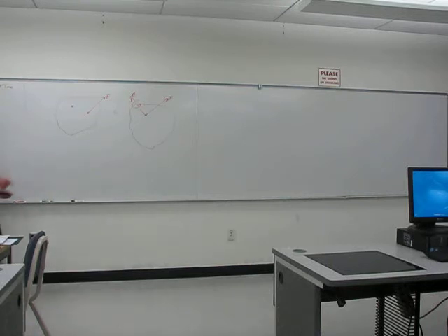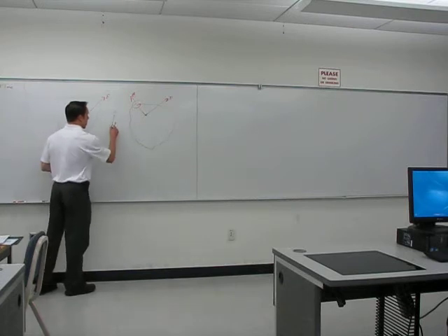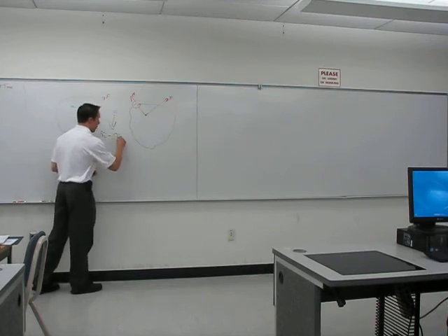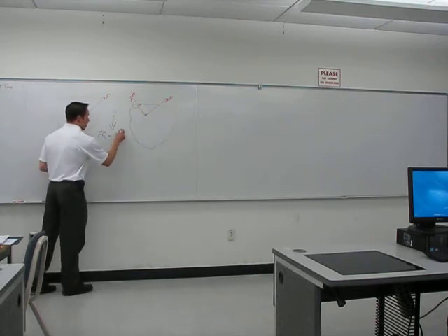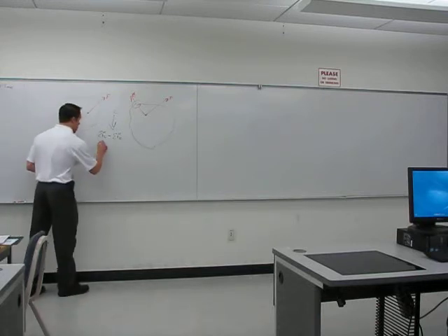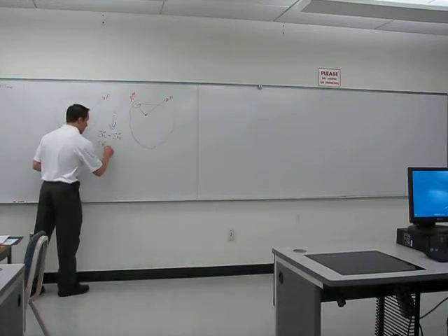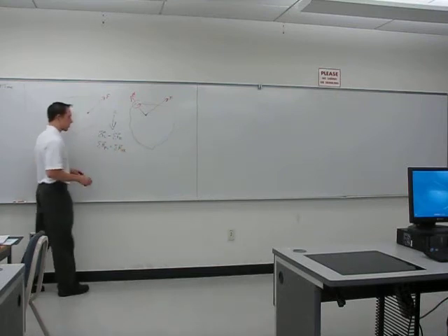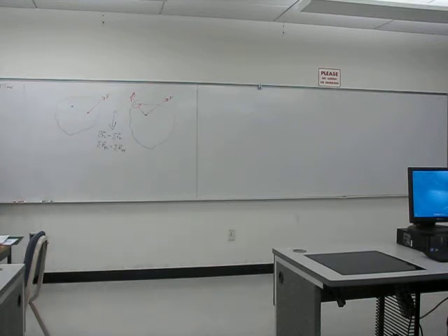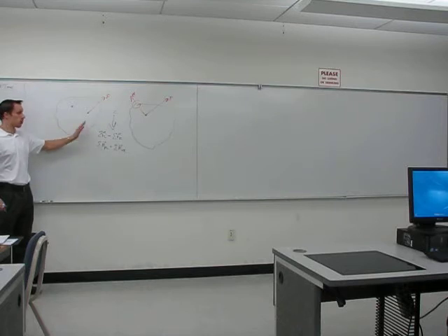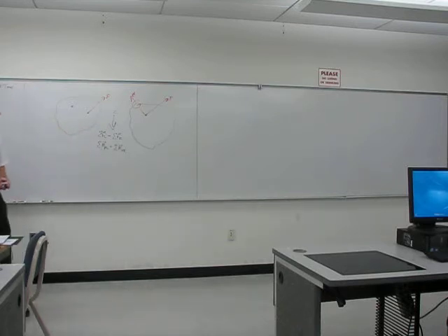Remember, this equal sign actually means two things here. This equal sign means that the sum of the forces in the left-hand picture has to be the same as the sum of the forces in the right-hand picture. And that's true for any direction, the x direction, the y direction, if it's three-dimensional, for the z direction as well. Also, the sum of the moments around any point in the left-hand picture has to be equal to the sum of all the moments around the same point in the right-hand picture. So you see these two conditions combined guarantee that the translation and the rotation of the rigid body is going to want to be the same in both cases.